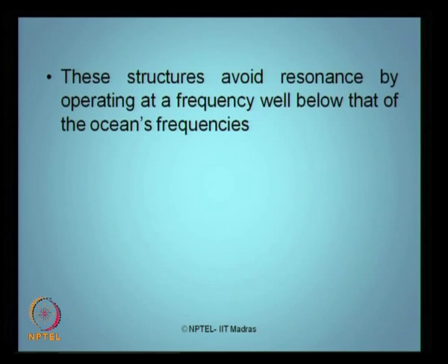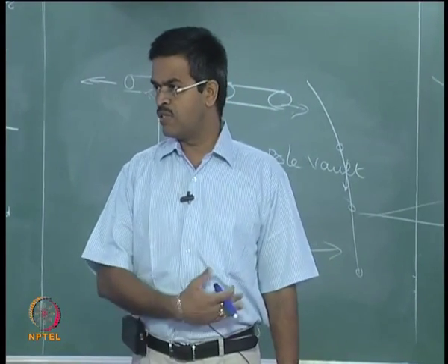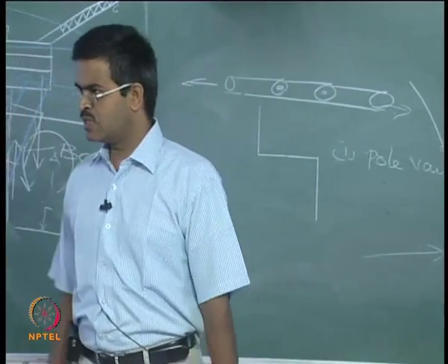Most interesting part is these structures avoid resonance, because the operating frequency of this structural system is well beyond the band frequency of waves. We will speak about this in more detail in the coming lectures, but it is a very important hint. It is a derived advantage: because the system becomes flexible, the frequency range of operation shifts away from the wave band. So, it is an advantage.